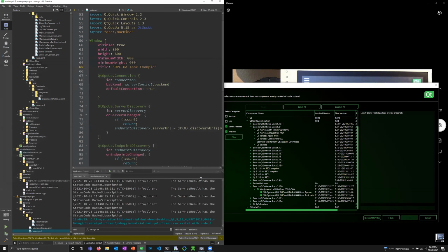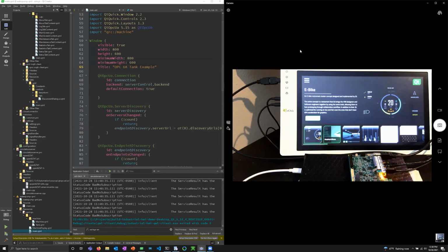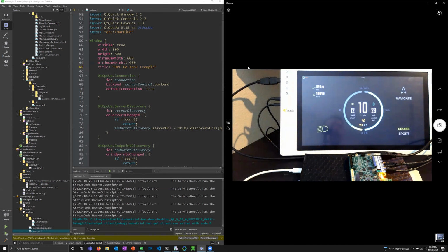So what I'm going to show today is a little bit of what Boot to Qt brings to the table. When you launch a Boot to Qt image, you have some things in place already on the device, an EGLFS application that we run, the Qt launcher. This gives you access to a number of great examples where you can see how well a QML application runs on your device.